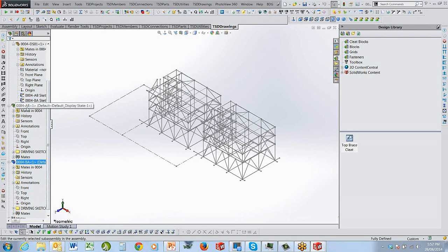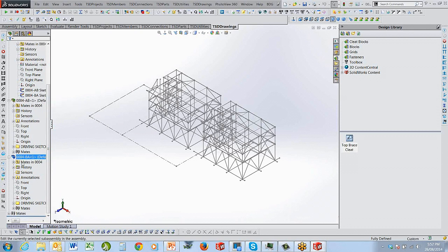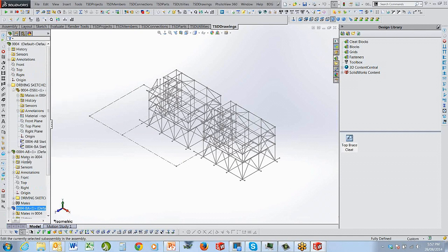So area AB would be structure, area AC would be piping, area AD would be civil, and you'll notice that I'm keeping the A, and obviously B is a second structure within the same project, and then I break that up into area BB, which would be piping, BA structure, BC would be say something like civil or mechanical or anything like that, okay? And that's basically how we use areas at this top level.